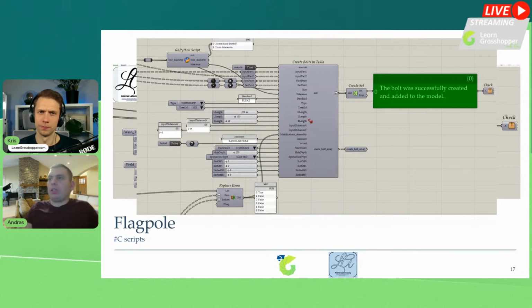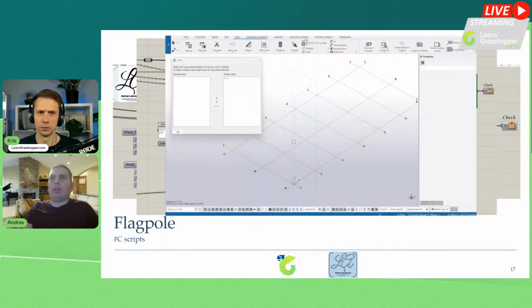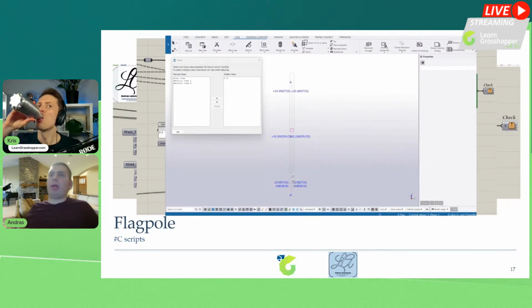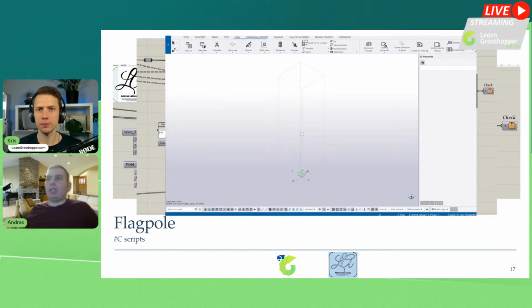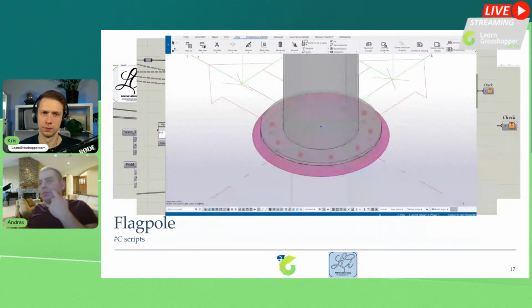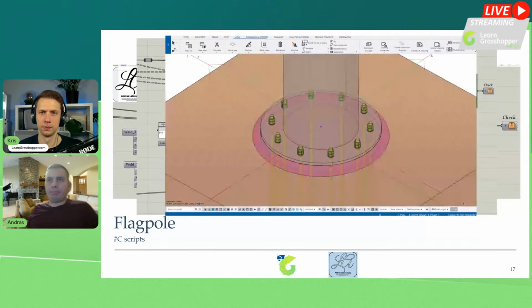In the next video, we can see how to modify the Tekla standard grid and how to create the views, plan and section views, open one of the views, and then model a steel rod and its base plate connection, like put a hole, put anchor, washer, nut, and weld.